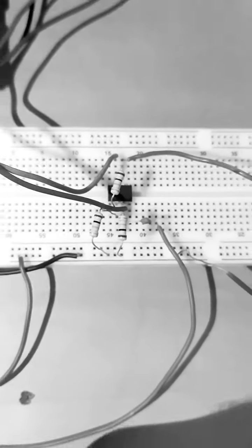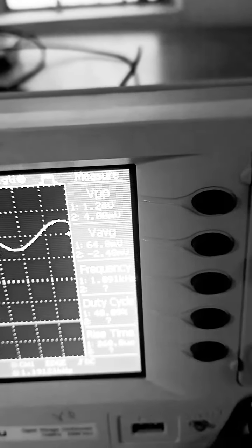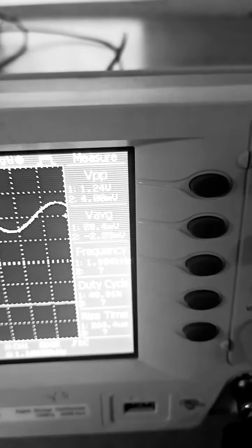Similarly, this is the next one, the connection for the high pass filter. As I told, I have just interchanged the resistance and the capacitance, and the resultant is a high pass filter. The procedure remains the same. I will set the frequency on the signal generator, and each time I will be noting the output voltage using your CRO or DSO.